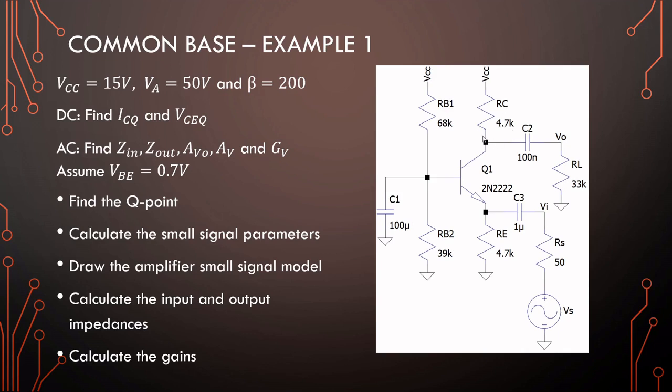but it still has a very large output impedance, which is not ideal, except if it's kind of a radio receiver and you're converting at this point to something else. The problem, however, is since this input is very small, this source is gonna be limited to 10 millivolts at all times. We don't have an option of increasing the input range of this amplifier, but it has a very large voltage gain. Okay,